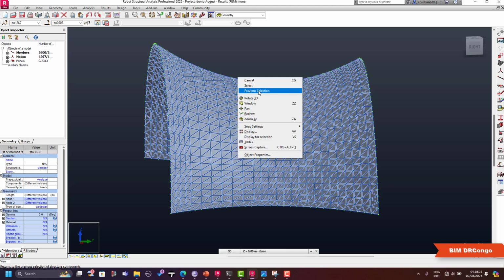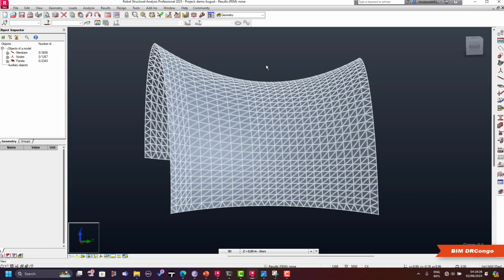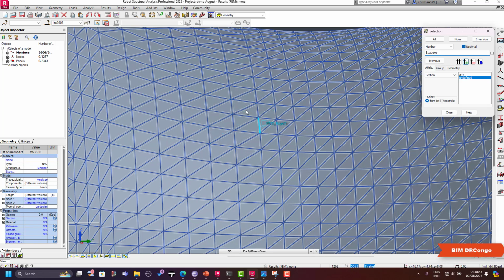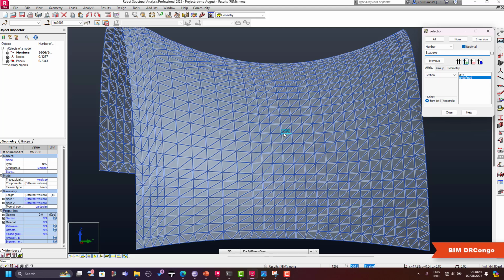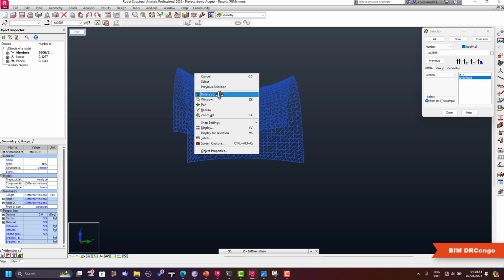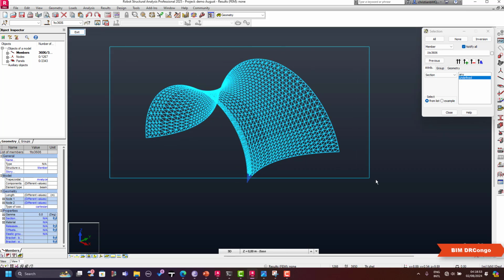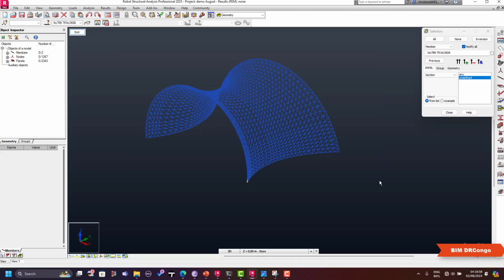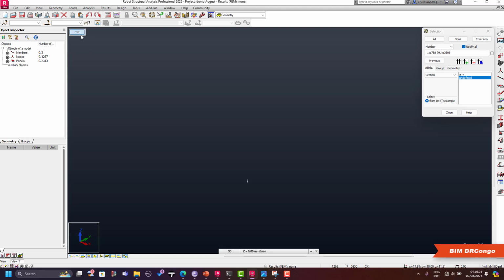So what I can do, I'm going to do the same things I did in our previous tutorial videos. I'm going to click here and click member and define member. When I click here, it recognizes all meshing members joined as members. I'm gonna delete all this to stay only with the concrete structure member panel, and click OK.